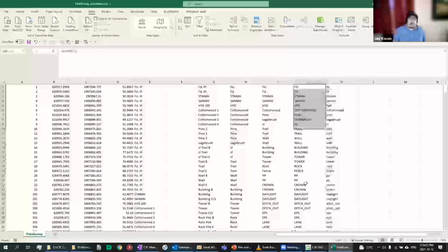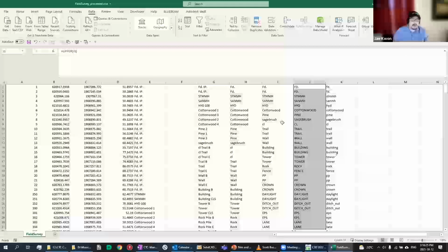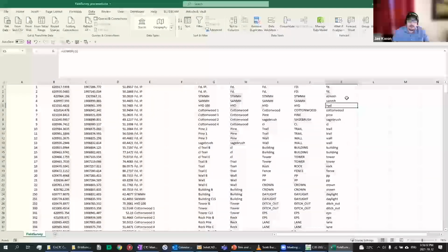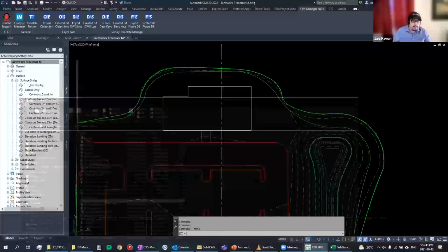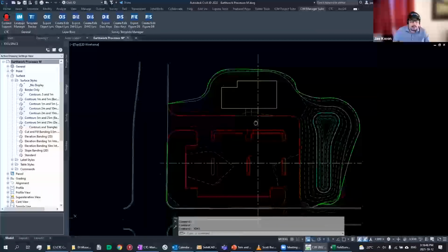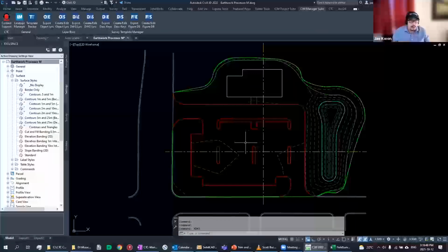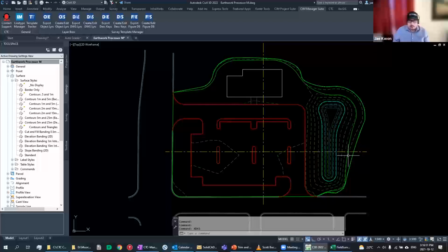So once you get one set done with all the properties that you want in the figure, in the description key set spreadsheet, you can copy that, manipulate it to get it all to lowercase, or maybe even proper case, first letter capitalized, and create copies so that you catch all sorts of variations, in case the surveyor puts it in the wrong way, you can catch that as well. But of course, we are trying to trim it down, so maybe you just have the uppercase as well. So, okay, that's basically the tool.